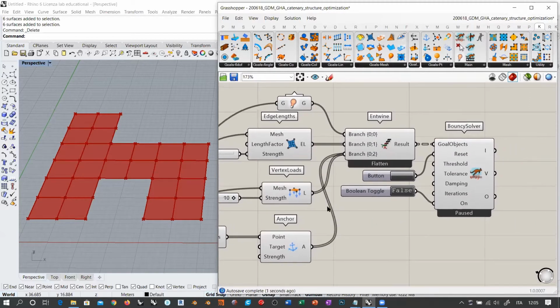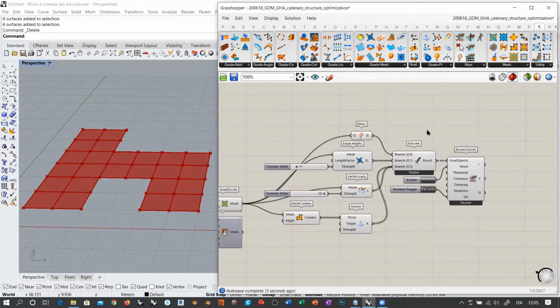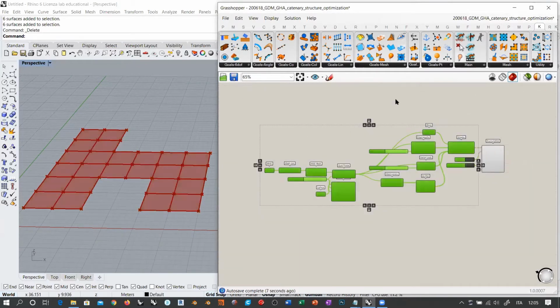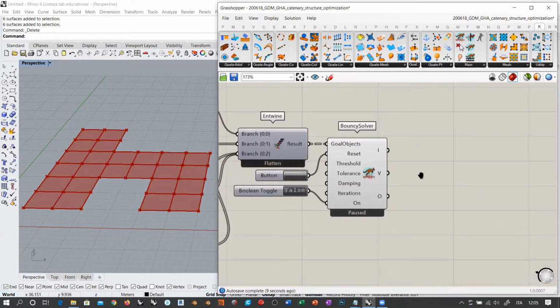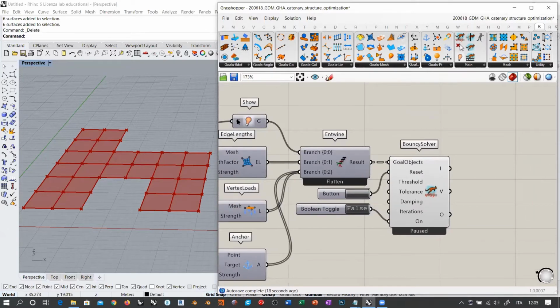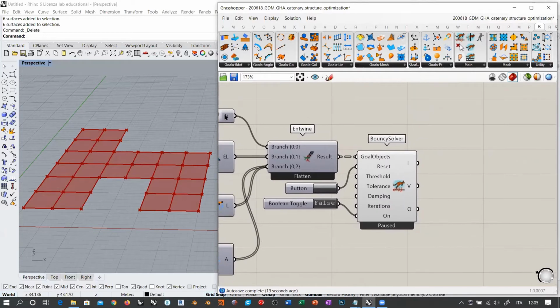Yeah, now it works. Normally, I do recommend that you turn off everything that's on the left of Kangaroo in order to concentrate on the actual preview. And I don't want to deal with the edges or the vertices and so on. I just want to see the final aspect of our mesh. So the mesh was plugged inside the first branch. So it's going to be the first available outcome of the simulation.